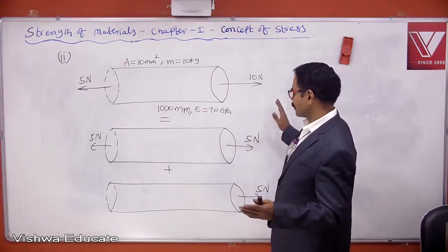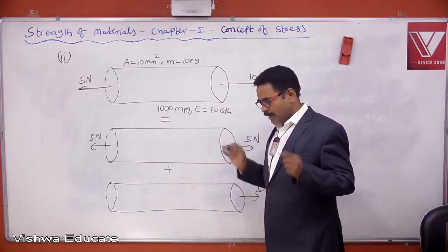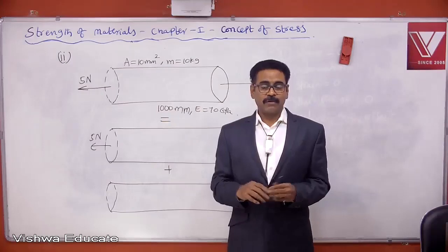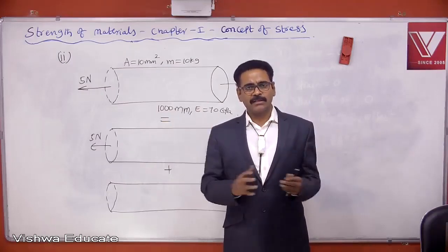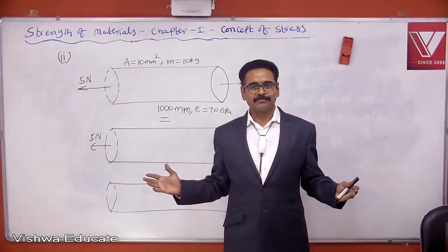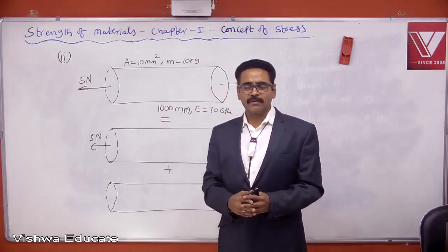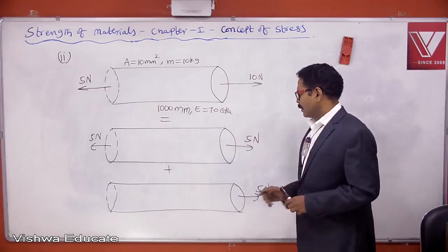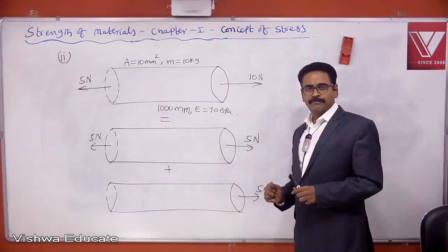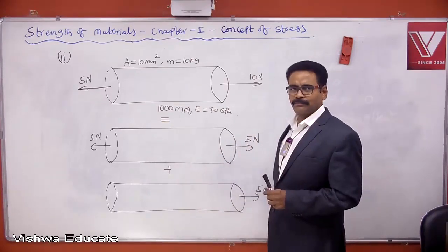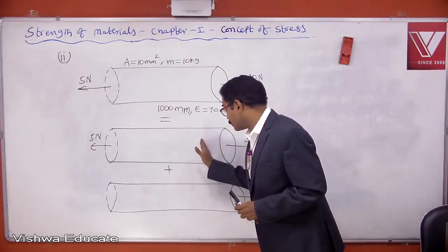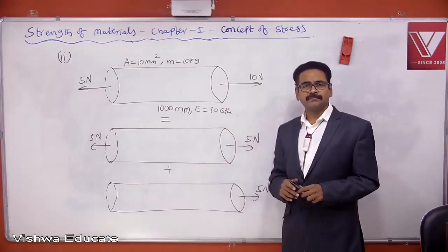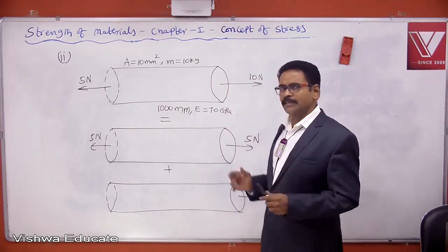This kind of thing is called the principle of superposition. In SOM, we can definitely use the principle of superposition. Why? Because in SOM, we deal with small deformations only. Wherever you use small deformations, there you can use the principle of superposition like this. Observe the first problem. You forget about the second problem. Observe the first problem. What is stress in this bar?